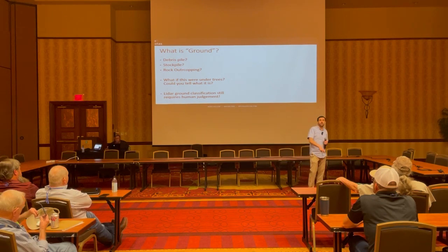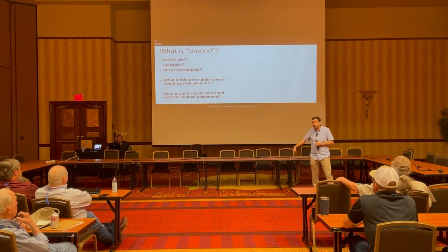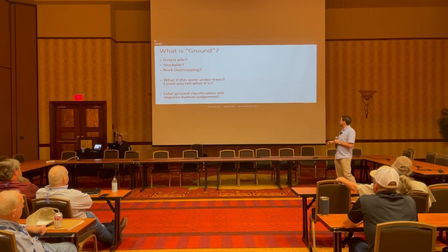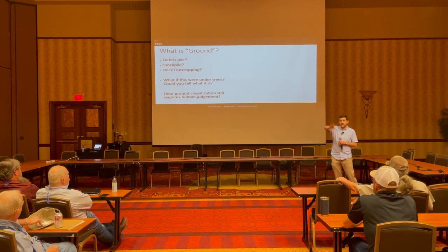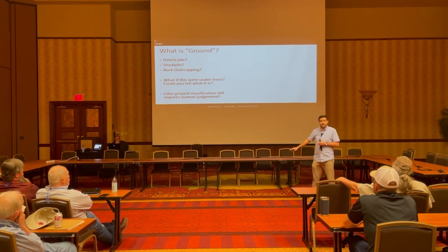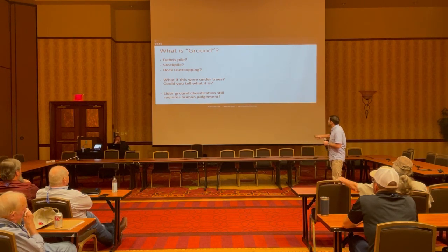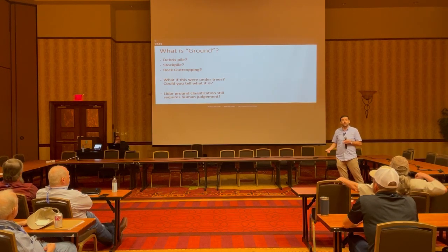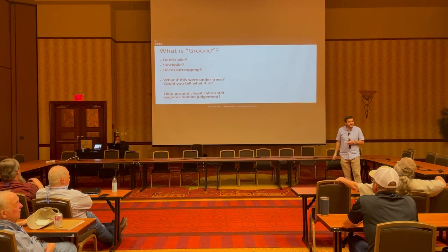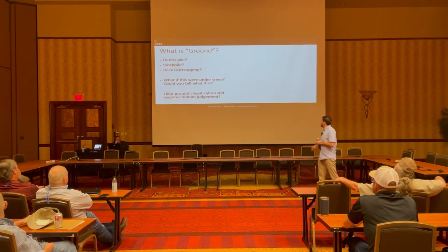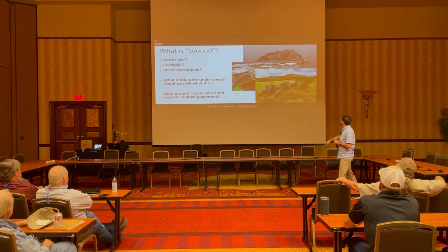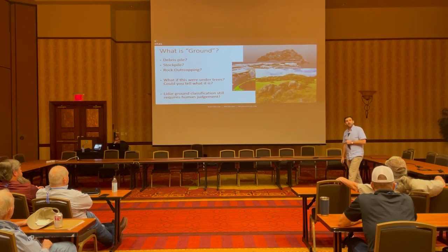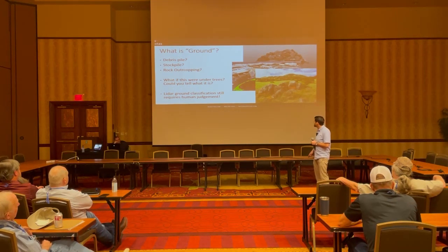Are they trying to figure out volumetrics of the debris pile so they can move it away? Or is it going to be moved by a construction site next week, so ignore it and you should draw the surface underneath? Same thing with stockpile measurements. Is the stockpile itself the ground, or do you interpolate a surface underneath so that you can create volumes? Or for rock outcroppings, is the rock the ground, or do you make a ground and then you mark the rocks for a different purpose? These are all kind of site dependent and something that humans are typically pretty good at. Those are some of the things where just deciding exactly what is ground winds up being a little bit trickier than just a simple mathematical calculation.